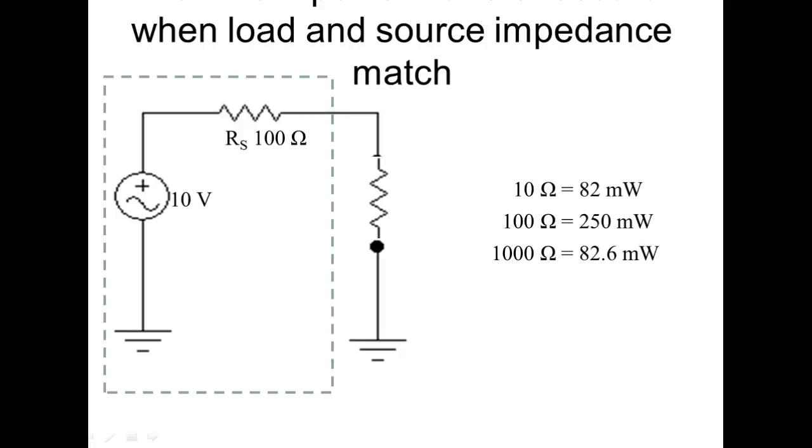You can't measure it with a resistance. If you measure it with an ohm meter, it puts out DC. So the capacitance of the cable you can't measure, right? And the inductance of the cable you can't measure. So that means when you wire up networking, by George, you better use the right cable, because if you don't use the right cable, you screw up your impedance matching. If you don't have impedance matching, then you don't get maximum power transfer to your load. And that's what we're trying to get to, right?